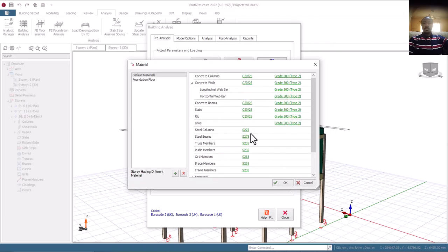And as I've done that, you can now see that all of this, from this place to this place, has been changed to Grade 20. Is that clear now? Alright, that's fine. Now, I haven't done the grade of concrete for this one. I need to do the grade of what?